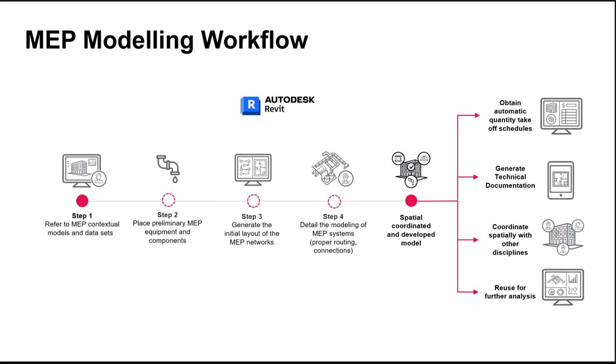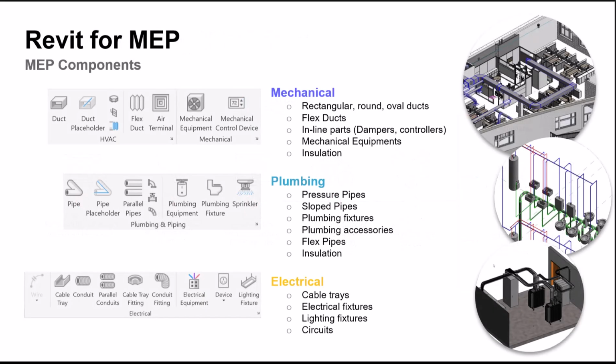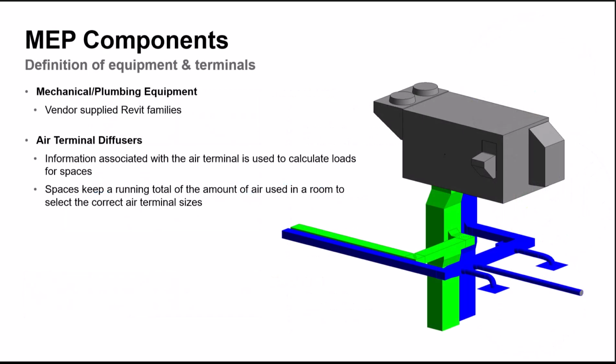Let's take a look at how components work in a BIM model. In Revit, MEP systems are represented by components specific to each discipline. These elements help create both the physical and the analytical models for the MEP systems. Using Revit's modeling tools, we can digitally construct all building services for the project, and after modeling, simulations and calculations can be run within Revit or using external programs.